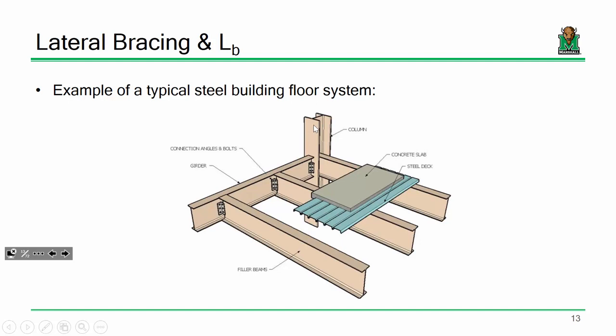Now, some other common options are, well, maybe you've got beams or elements framing into a given segment, like beams in a floor system. So, for instance, if I'm looking at this particular girder, these floor beams are framing into that girder and serving to brace it from going side to side. Make sense?